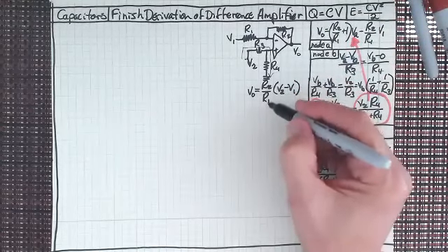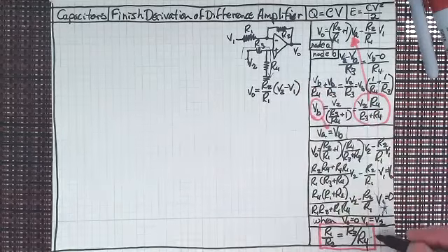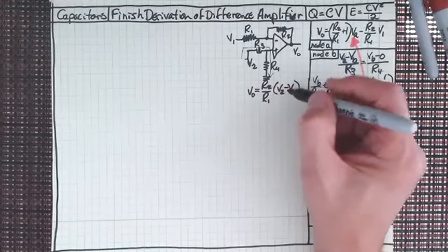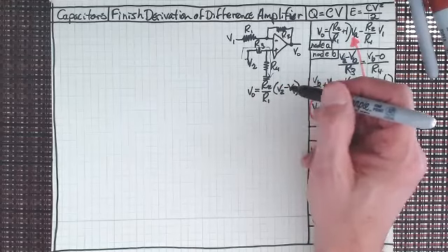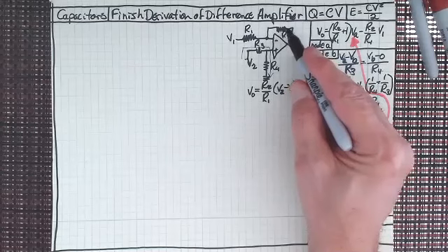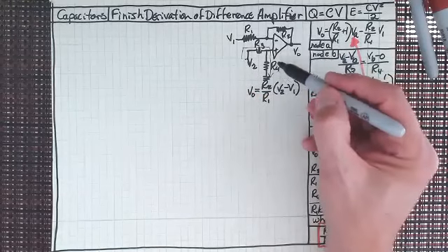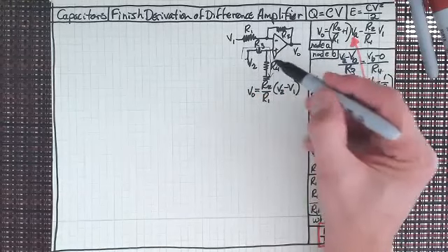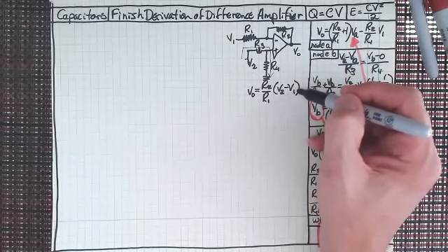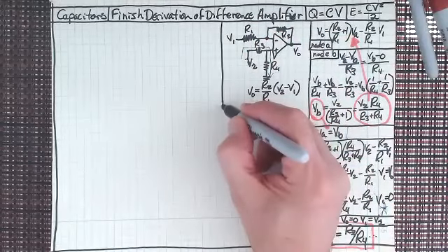But if I did make those equal, if R1 and R2 are equal to one another, and R3 and R4 are obviously then, due to this requirement, going to be equal to one another, then I could make a subtraction, right? So V out is just going to be V2 minus V1. But what if I did want to amplify the difference? Well, then I could keep R2, let's say R2 is 10,000 ohms and R1 is 1,000 ohms, right? And let's say that down here, this is 1,000 ohms and this is 100 ohms. You see what I'm saying? We've got to keep them in the same ratio. Then I would get 10 times the difference, wouldn't I? Does everyone see that? So I wanted to bring that up and finish that off first.